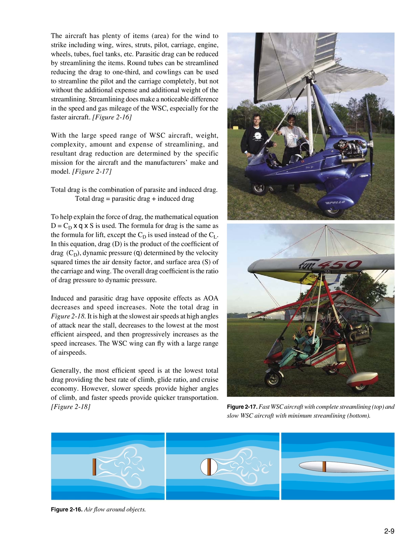The WSC wing can fly with a large range of airspeeds. Generally, the most efficient speed is at the lowest total drag, providing the best rate of climb, glide ratio, and cruise economy. However, slower speeds provide higher angles of climb, and faster speeds provide quicker transportation. Figure 218.